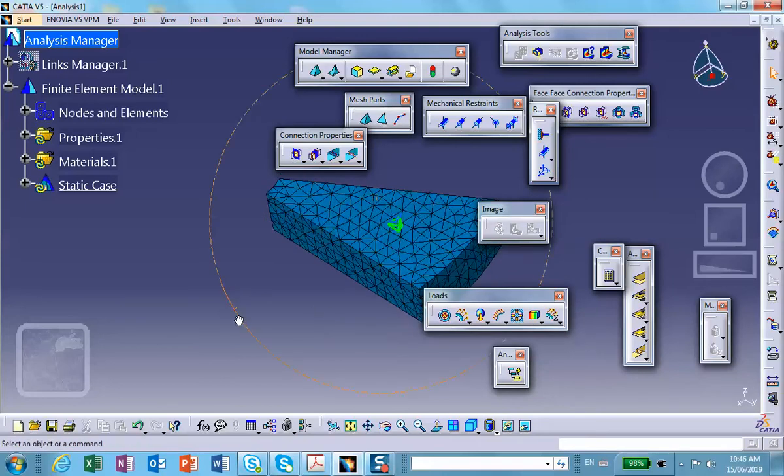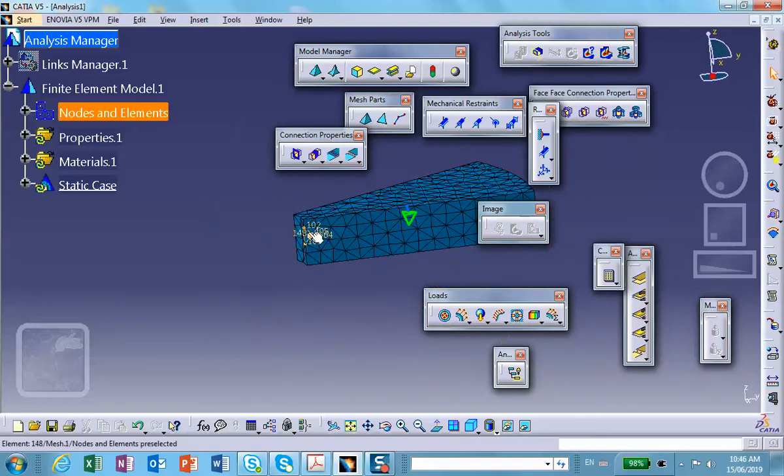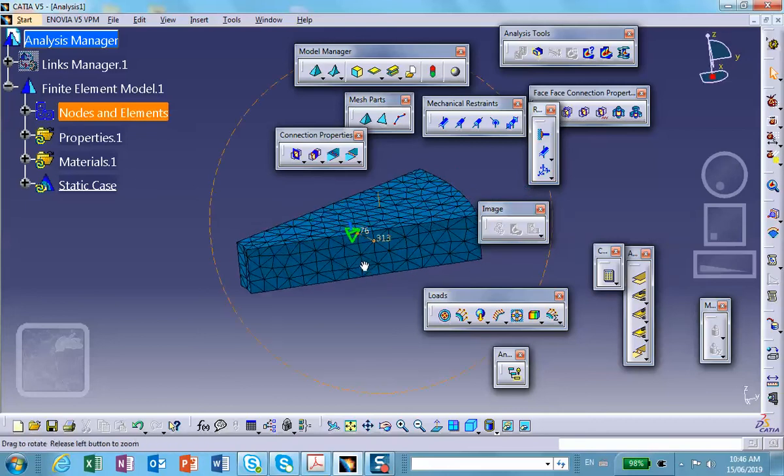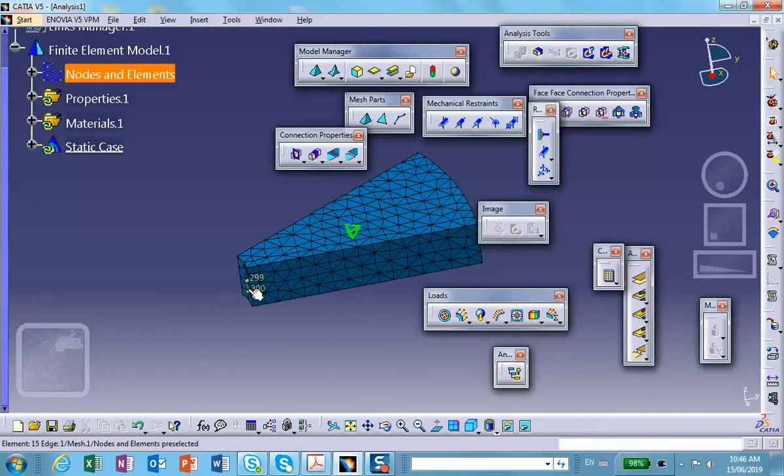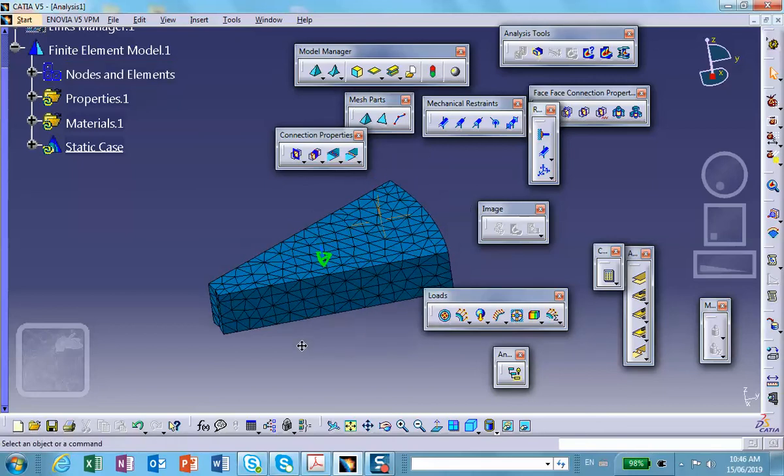Now, this is a terrible mesh because we know that there is going to be a severe stress distribution at the inside of the hole, so we need a fine mesh in this area. I still have not told you how to do fine mesh in a particular area. The trick we're using, we make everything small, which is not a good strategy. But let me try it.